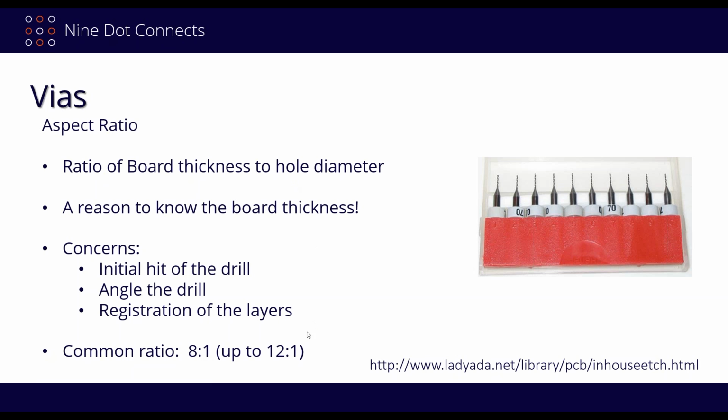From 8 to 1 up to about 12 to 1, a lot of companies can do it. However, you're going to pay a higher cost for it. And anything from 12 to 1 and beyond that, you're going to pay top dollar for it. So it all depends on the type of board you're building. If it's a Happy Meal toy, I don't recommend you go to 50 to 1, right? Maybe some companies can do that, but that'd be a very expensive Happy Meal toy, right?